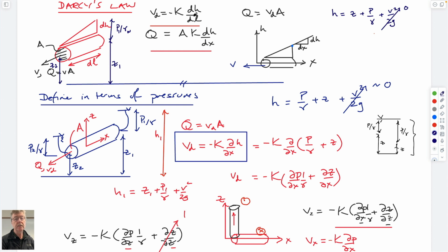So we can define Darcy's law in terms of the change in head or pressure, which is really the head over the length. It's negative because it flows in the opposite direction from the positive pressure gradient, head gradient. And if we multiply this by a cross-sectional area, which is the end of this tube, we get a volumetric flow rate. And so, as we said, if we wanted to calculate the mass rate of loading, it's equal to a volumetric flow rate multiplied by a concentration. And the uppermost concentration would be the maximum solubility of that component in water. So immediately, if we know what Q is, we'd be able to calculate what the mass removal rate is and what the mass loading downstream is.